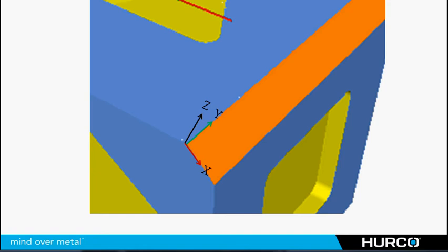Here we see that I've moved over to that corner. Then I rotated 45 degrees positive, which is around the Y, or to the right side around the Y-axis, and then I will program. Notice what happened to the X. It also rotated, much like it did in our first example. It rotated 45 degrees also. So that's our X positive direction along the edge of that chamfer. So let's go ahead and program that.